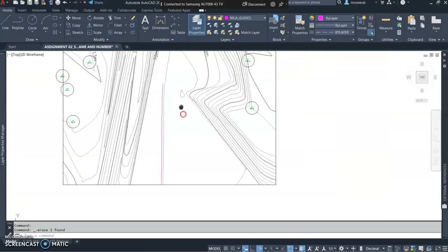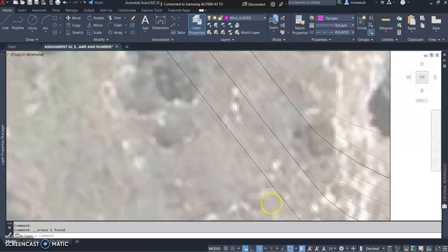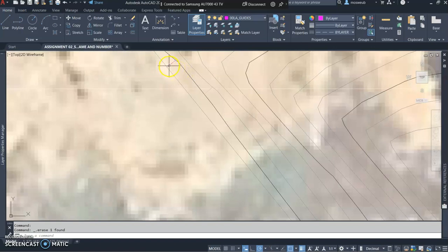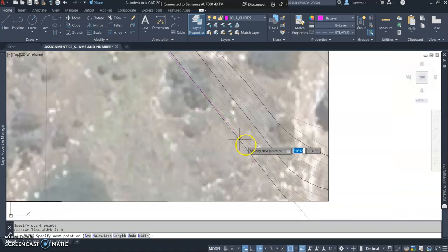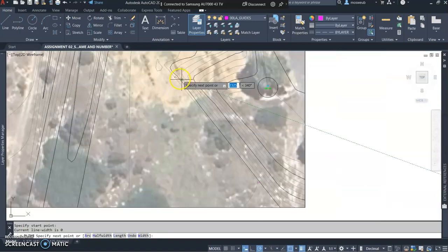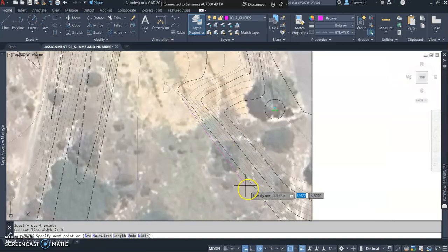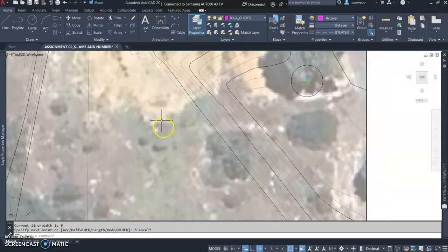and then you can use what is called the boundary command in AutoCAD to create an enclosed boundary that you will then hatch at a later point. And this is a shortened method of drawing an outline for that particular area. So instead of manually drawing a polyline all around or creating an enclosed polyline, what you can do is just type in boundary.